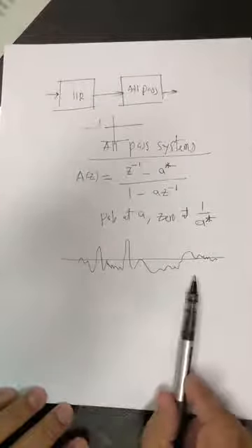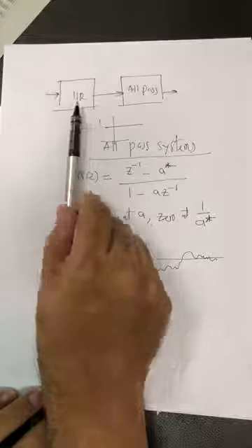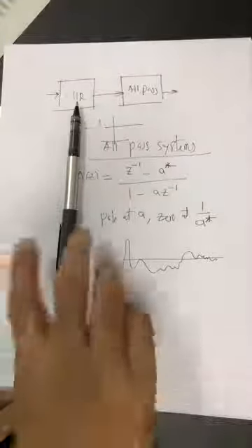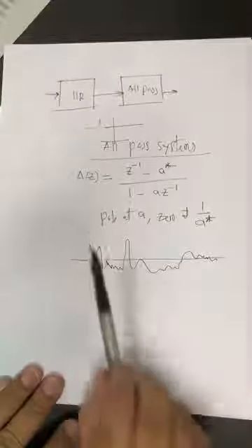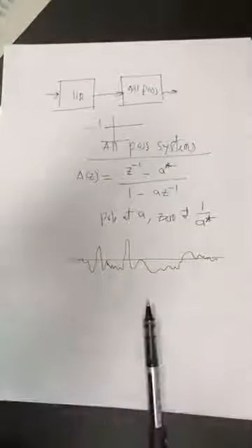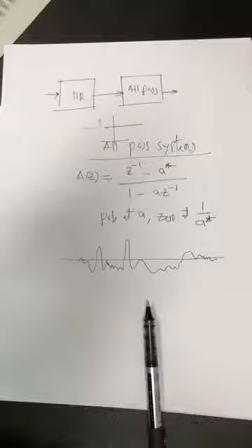And so you either use an IIR filter which keeps in mind that the frequencies you are going to pass must not have their phases distorted, or you use a phase compensator, or you use a linear phase FIR filter. So it is your choice which filter you use, but you must always plot the overall phase response or the group delay to get the comfort that your signal processing is not going to corrupt the shape of the signal.